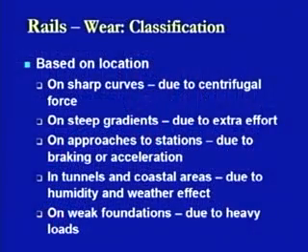Then the next reason, in the case of location, is weak foundations. Now, the foundation is the ultimate point which is going to take the whole of the load which is coming from the top. If the foundations are weak enough, then they will not be able to sustain the loads coming from the top, and there are going to be deformations in the overall structure. When the deformations are induced, they have a further effect in terms of track irregularities. These track irregularities will further induce stresses. So, this is a sort of chain reaction which is caused by one reason.